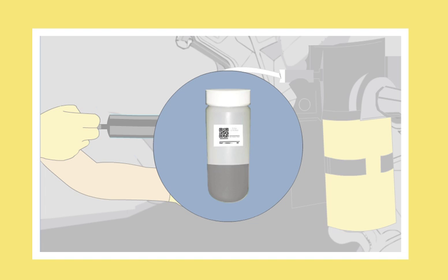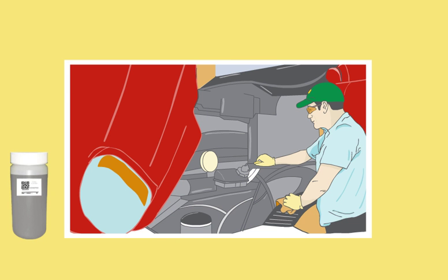Continue pumping until the sample jar is 3/4 full. Hold the pump upright in order to avoid residual contamination from the vacuum pump. Finally, unscrew the sample jar from the vacuum pump and tighten its lid securely.